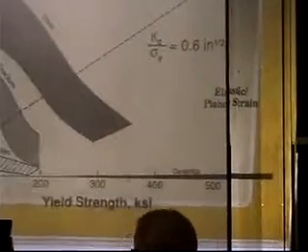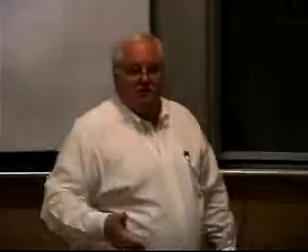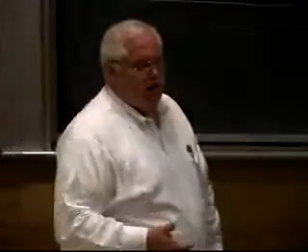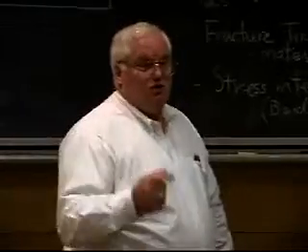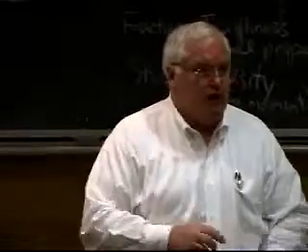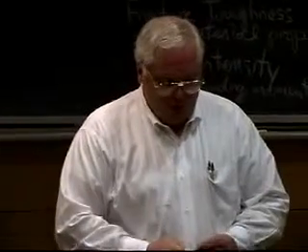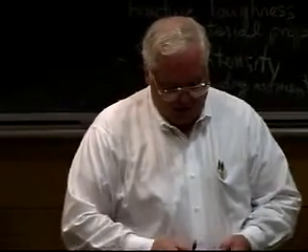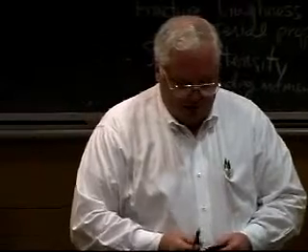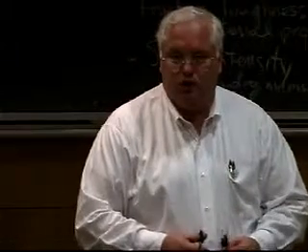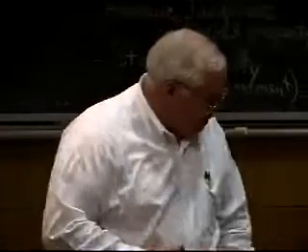Typical fracture toughness of a steel might have units of 100 KSI per square root of inch. A good ceramic is 1. That's 2 orders of magnitude lower fracture toughness. We're going to talk in a little bit about why ceramics are not necessarily structural materials, although there's an exception to every rule.